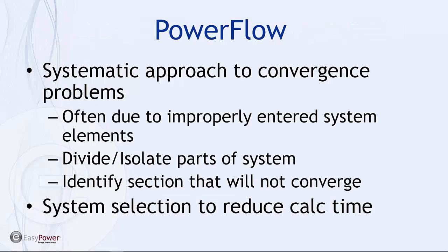So what we're going to be talking about is essentially a systematic approach to convergence, and what you find when you start to do PowerFlow analysis on some systems is that it can get thrown out of whack because some system elements have been improperly set up. Consequently, the PowerFlow module itself is a good debug tool in terms of identifying anomalies in our database initially when we're doing data collection for a short circuit or arc flash study.